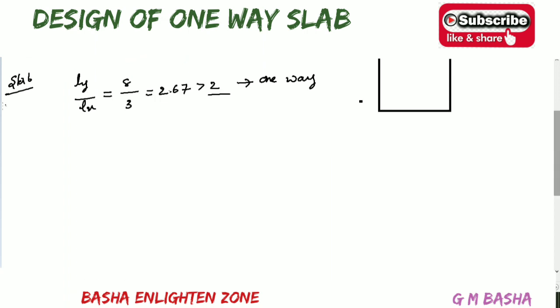So again, the next step is the thickness of the slab. According to Indian standards, for example, for two-way slabs it is given in the IS: for mild steel the span to depth ratio L by D will be 35, and it is multiplied by 0.8 for Fe415, which means L by D will be about 28.